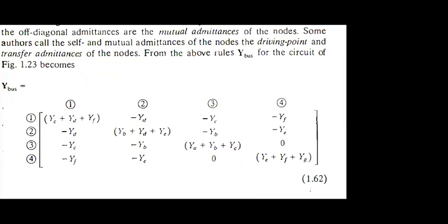I think you have got a clear idea regarding how to generate, first of all, the impedance diagram, then the reactance diagram after simplification, excluding load as well as shunt parameters like admittance and other resistance. These three you have to exclude to generate the reactance equivalent circuit of the impedance diagram.